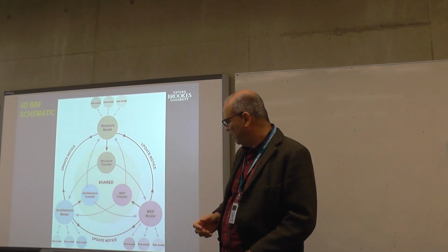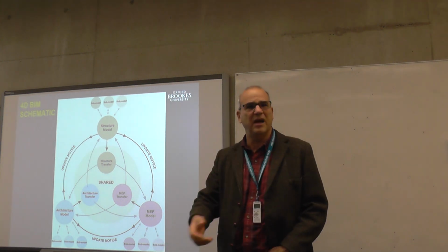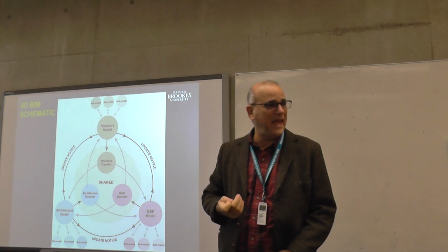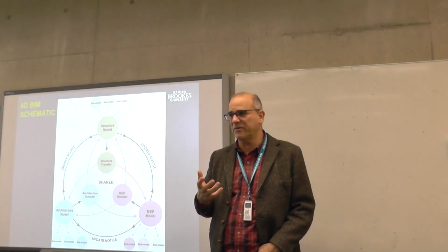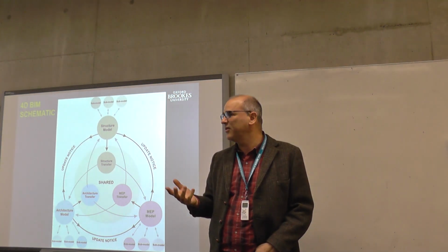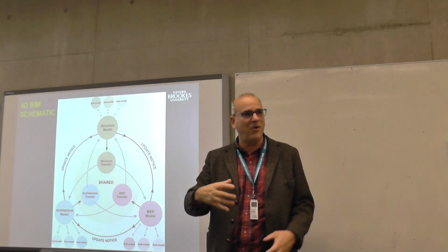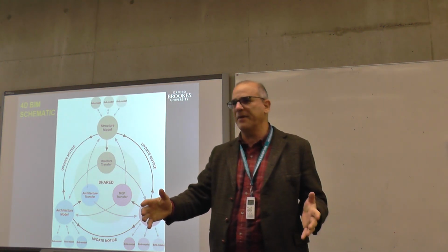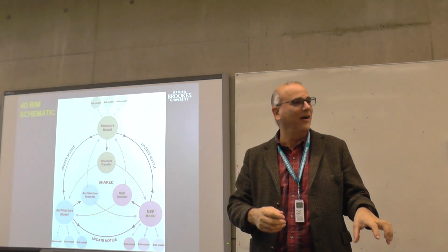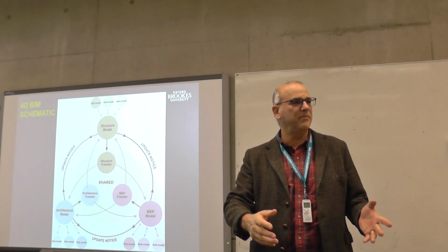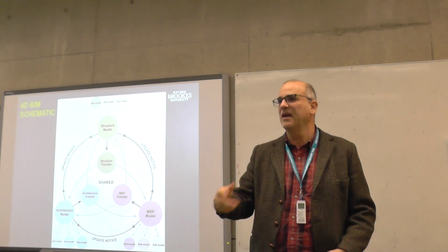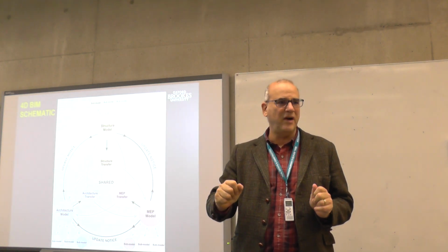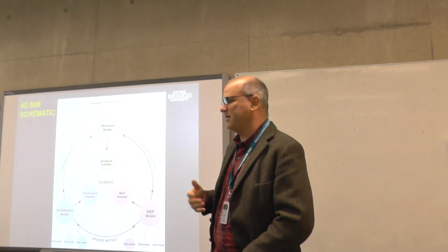the shared BIM model. So someone could propose something, someone could do a quick, rapid evacuation. It's a great thing to know: how long would it take if we sound an alarm to evacuate this building if it was fully filled with students? Are the stairwells big enough? And there are actually software models that will allow you to do this. You fill a building up with people, you blow up a corner of it, and you see how quickly people can get out. You computerize this system so you can test, if you blow up 2 corners, is it still evacuable? So you can actually simulate disasters and see.